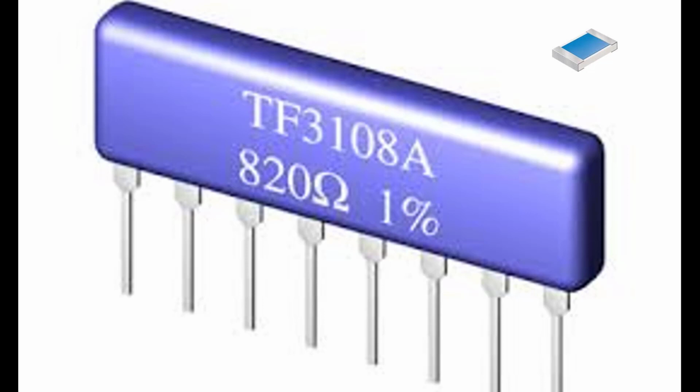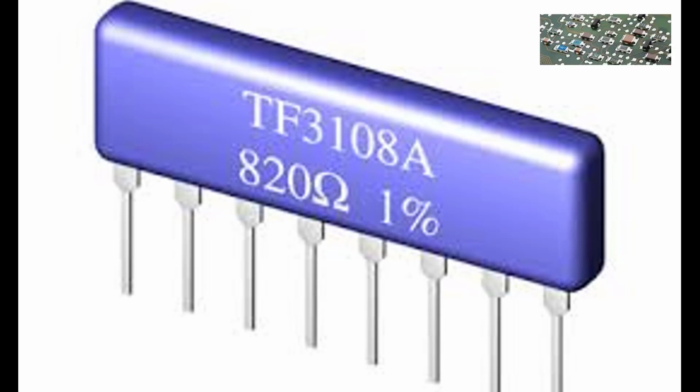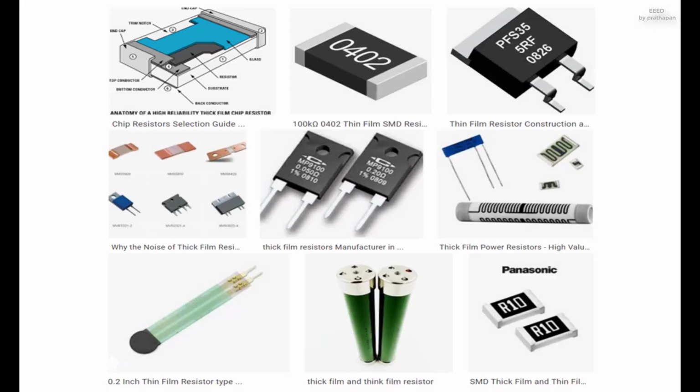Thin film resistors are made by sputtering, a method of vacuum deposition, the resistive material onto an insulating substrate. The film is then etched in a similar manner to the old, subtractive, process for making printed circuit boards, that is, the surface is coated with a photosensitive material, then covered by a pattern film, irradiated with ultraviolet light, and then the exposed photosensitive coating is developed, and underlying thin film is etched away.